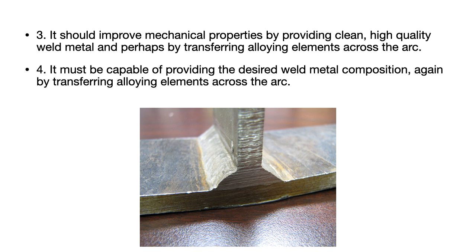So one of the basic functionalities of the flux which is added is that it shall increase the strength of the weld produced by an alloying effect. It shall also be capable of producing weld metal compositions, due to addition of certain alloying elements, so that the composition of the base metal shall not be very different from that of the weld which is produced.